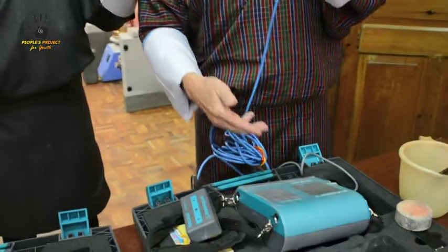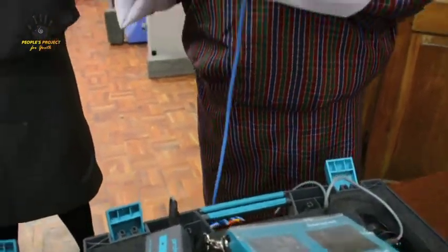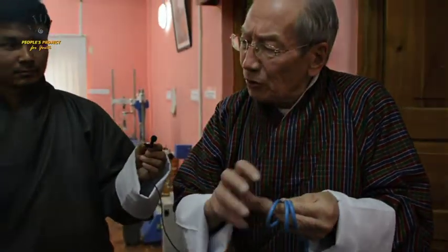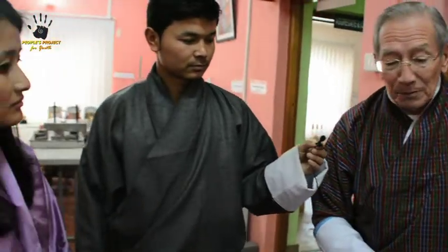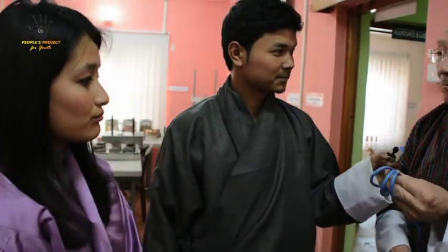And this box down here measures the reactance of this coil. So when it gets near an iron bar, the resistance of this coil to alternating current, in other words, its reactance, increases, and I get this showing up as a figure on this machine, so I can detect where the iron bar is. And if you had an iron bar in your go there, we'd be able to find out.